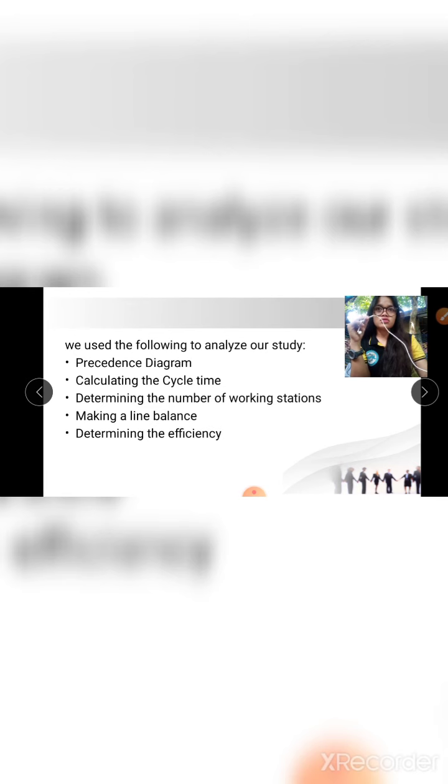As the assumptions in making a case, the method of assembling process for the camera module comprises the following steps: placing the substrate on a positioning die with 90-second process time, irradiating the lens assembly with parallel rays of light with 40-second process time, placing a lens assembly comprising the convex lens in an axial direction with 60 seconds process time, measuring the light intensity of light passing through a spot hole by means of a light sensor accommodated in the positioning die with 30 seconds process time, determining an optimal position of the lens assembly on the basis of an obtained light intensity curve with 70 seconds process time,